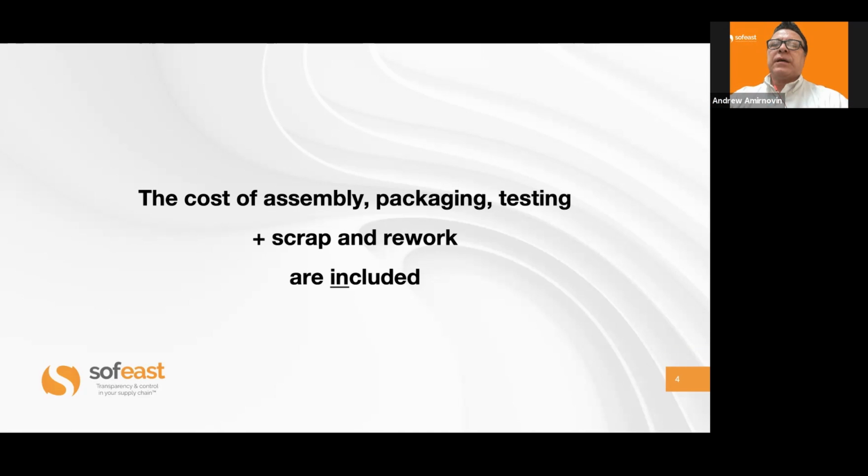Yes, absolutely. Well, the cost of the assembly and packaging and testing, scrap and rework are also included in the unit price. Right. So that means if your product is designed in a way that doesn't call for very mature processes, and there's a lot of rejects, you have to be aware that in the end you will bear the cost of these rejects, right? So think about that. Also, if assembly takes 2 minutes rather than 30 seconds, because you didn't really pay much attention to design for assembly, you're going to bear the cost of that, basically.